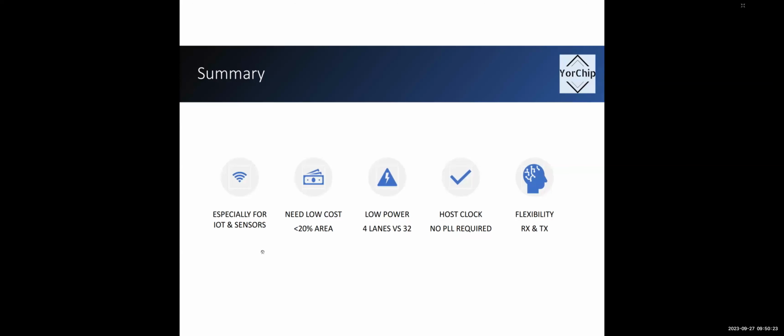To give you an example of the use case for this: let's say you have an FPGA trying to read data from an ADC and pass certain data to a DAC, in a system that is synchronous. This link lets you read the data from the ADC and pass it through to the DAC without any adaptation FIFO, assuming those sample rates are all synchronous. So it simplifies latency.